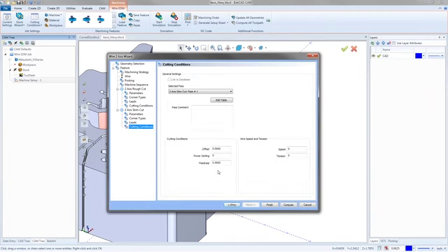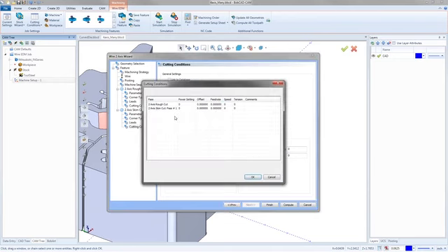Next, we have our cutting conditions. Now, the reason I wait until I get to this point again is because if I go into the edit table now, after I'd normally have defined how many skim passes I'd have, if I put 3 in here, I'd have 3 skim passes now. Earlier, I'd only see the 1 because at that point, I haven't defined the amount of skim passes I want.